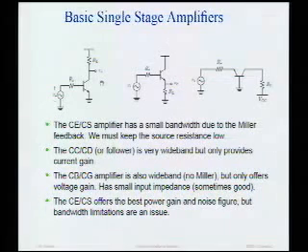So even if we don't have a limitation coming from the source, from the load we have output capacitance, and that produces a pole with that load resistance. So that's bandwidth reduction. And you're precisely right. If I want to get high gain, I need to use either a lot of current to get lots of transconductance, or I need to use a large resistor.